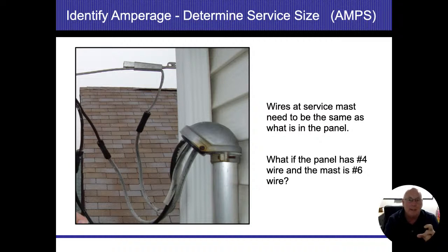I also like to look at that tag on the meter panel. It's a tamper tag. If I see that that's cut or broken in any which way, then I know that somebody was in there doing some sort of work. In our area, the electric company is the authority having jurisdiction. They're the ones that can approve or disapprove any sort of hookup. So if they want to have smaller wires feeding their system, they could do whatever they want to do. They're the authority having jurisdiction. But for me and for our company, we don't want to take ownership of issues. So if we see something that's out of the norm, we're going to document it, plain and simple.